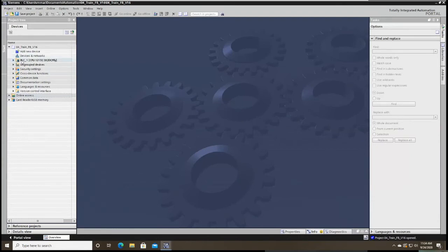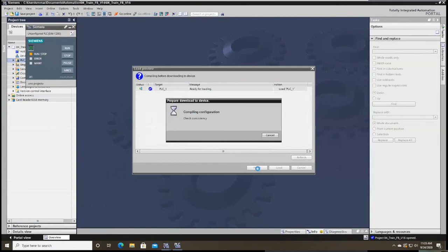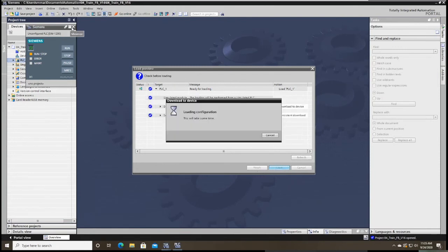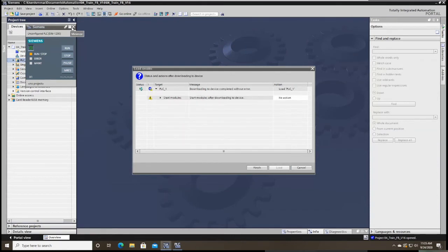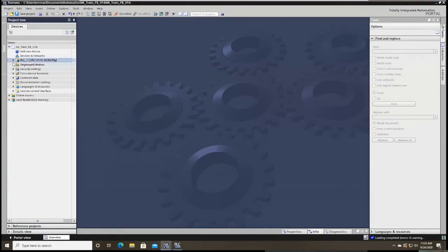You may be asking yourself, why would there be a function, or in this case, a function block that has a designated memory area? And the question's pretty straightforward. Say you had a function, kind of similar to the pump block that we had, except it's a function block now, and there are a specific set of parameters for each pump. You can use the associated data block for each one of those pump calls to store data regarding that pump. It's just a means of having a preset of properties for different pumps, because not every pump might be the same. It might not have all the same parameters that the other pump may have, and you'll see what I'm talking about exactly in one second.